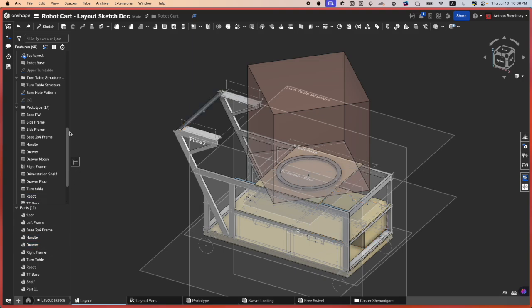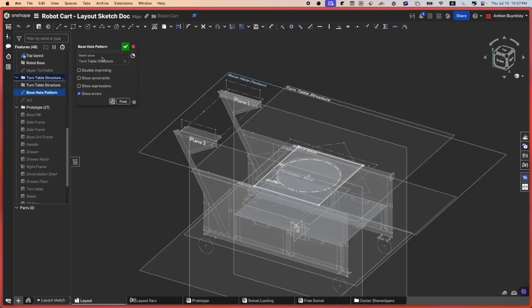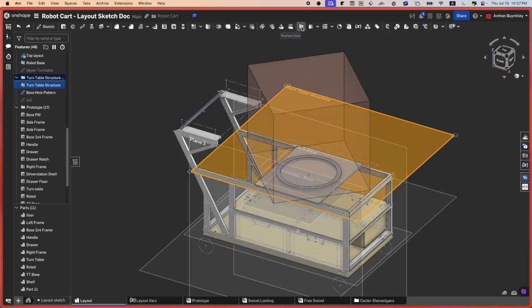And if they do break, your sketch also breaks, which is a pain because it is a layout sketch, which is kind of like the original sketch of your robot. So the only things you should be selecting for the sketch plane is quite literally planes, which is why you will need to be using the plane feature a lot. Is that good? Yep. All right, cool.